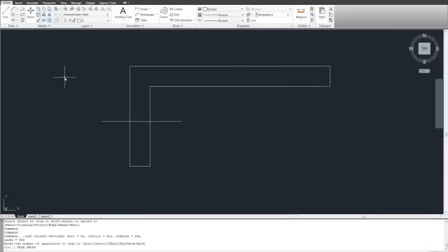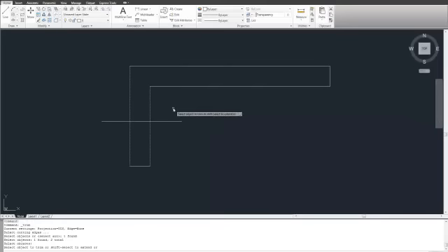If I undo that, I can do the opposite, of course, and trim the center piece out and leave the two end bits. So I would use the trim tool, select the two cutting planes, of course, and then right click and then click on the piece in the middle and right click and select enter, and there I've just left the two bits on the outside. I want to get rid of those now, so I will erase them. And that's all for now.